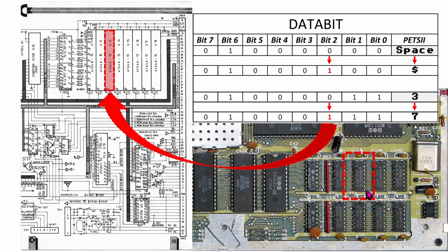Back in the day, we just cut all the pins here with a sharp cutter, and then we just desoldered each leg. And in some cases we didn't even bother to take out the PCB when we did this, because we were just removing the pins from this side. We placed in a new chip and we just soldered it from the top, as all the holes are through-plated on this. But I will take this out and I will save this chip, because it's an interesting fault with a RAM chip, and I probably will want to do some debugging on this chip later when we come as far as that.